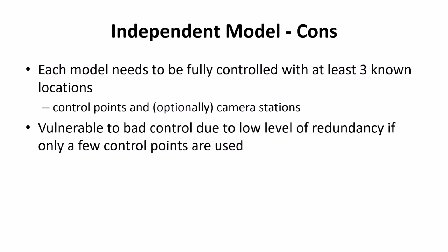And if you have poor ground control, you don't have much redundancy if the surveyor of that ground control made a mistake. So this method is vulnerable to bad ground control if only a few control points are used.